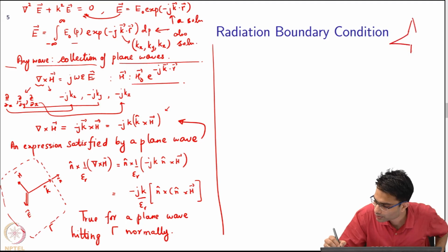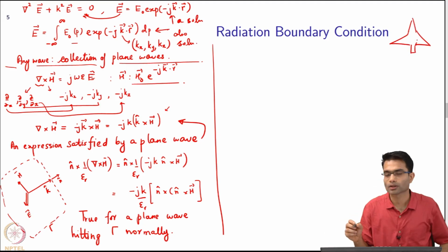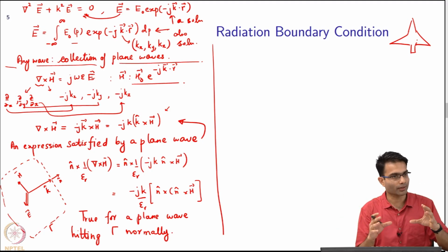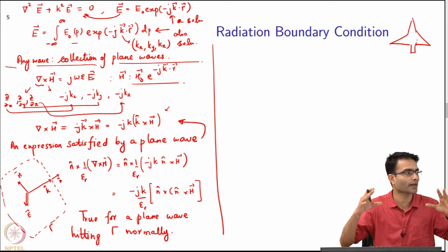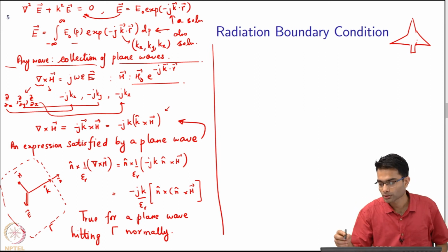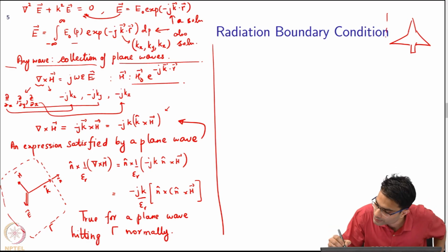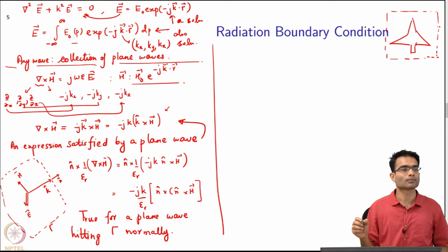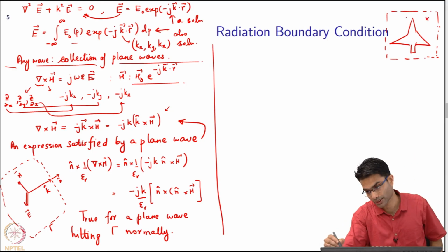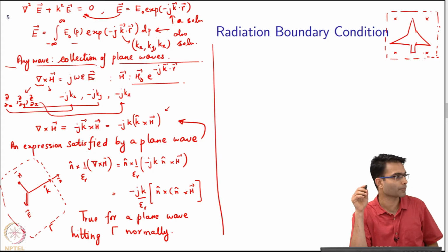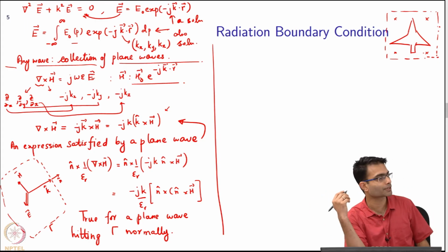Now, the question is, where should I draw my computational domain? Should I make it tightly fitting with the aircraft or should I expand it a bit? The computationally inefficient but easier thing to do is to make my domain like this. So when I do this, I have to discretize all of this free space region, and that's a price I pay. We'll come later to the advantages and disadvantages of doing it.